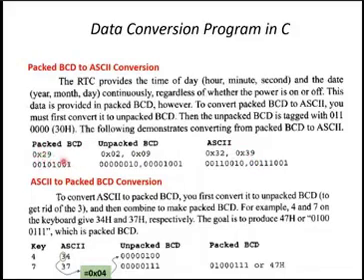Using the RTC problem, since we know the RTC provides the format of time of day, starting with hour, minute, second, and then the date, followed by year, month, and day. So everything needs to have its own character and numbering. So how do you transform? Normally this data is provided in packed BCD. Packed BCD is 8 bit.